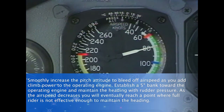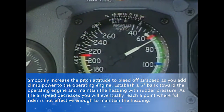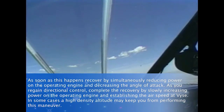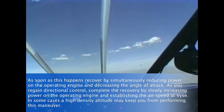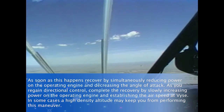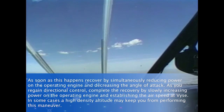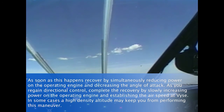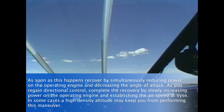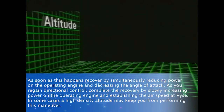As the airspeed decreases, you will eventually reach a point where full rudder is not effective enough to maintain the heading. As soon as this happens, recover by simultaneously reducing power on the operating engine and decreasing the angle of attack. As you regain directional control, complete the recovery by slowly increasing power on the operating engine and establishing the airspeed at VYSE. In some cases, a high-density altitude may keep you from performing this maneuver.